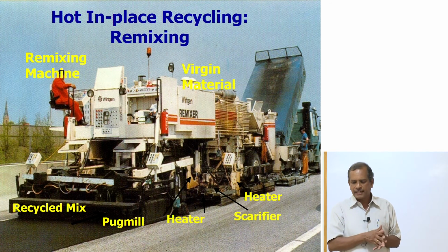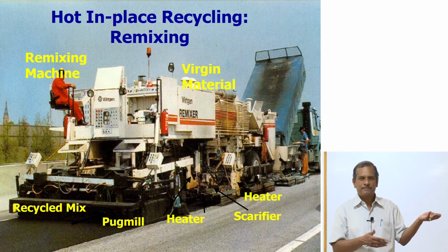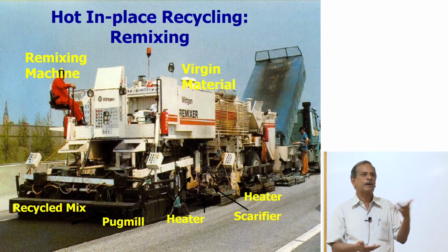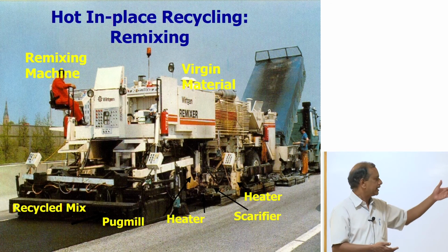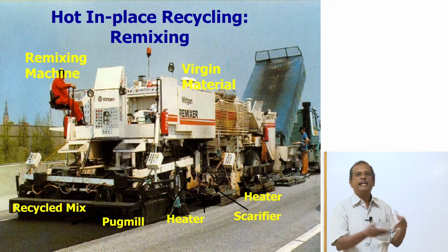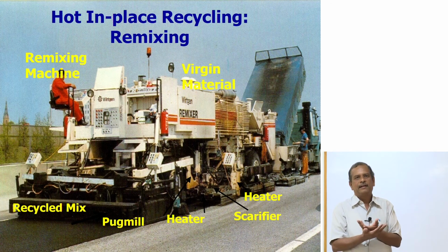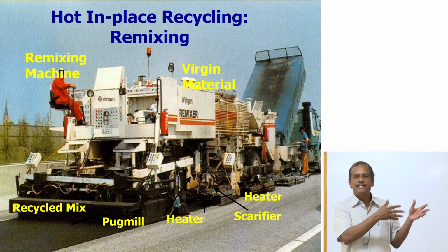So, the technologies that have to be adopted in the years to come are, number one, you have to reduce the construction either by stabilizing the subgrade, using geocells, geogrid, geosynthetics, using modified binders, or in the case of recycling, adopt white topping, or recycle the material either by hot recycling or cold recycling. Any of the technologies can be adopted. So, all these choices depend upon the proficiency of the civil engineer who is in charge of the project.